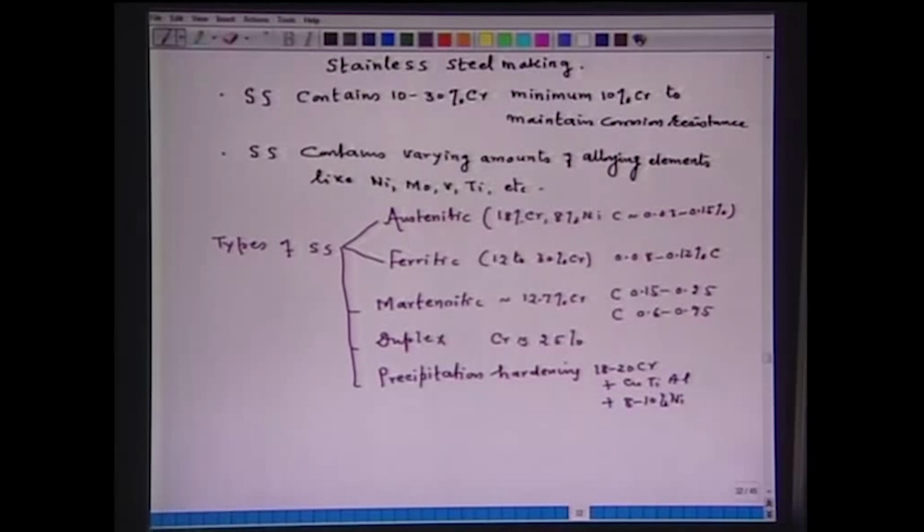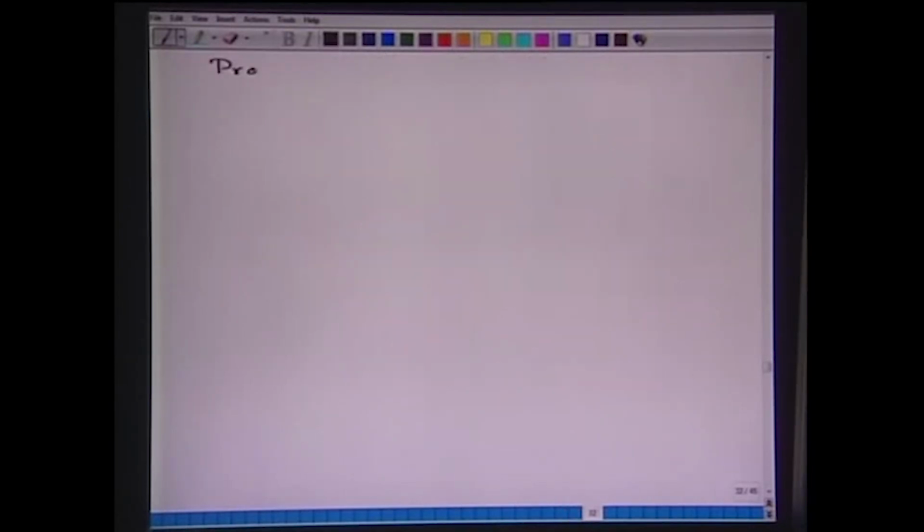Now, about the production of stainless steel. Electric arc furnace is used for production of stainless steel through melting stainless steel scrap. Hardly any refining was required because stainless steel scrap was available of the composition which is required for the product; it was melted, and stainless steel of that particular grade is there.